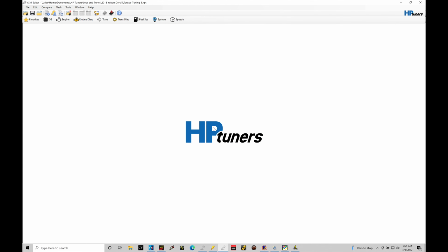Okay, so let's get started. We're going to be taking a look at our airflow correlation calibration within this tutorial. This is going to be specifically relating to our P0068 DTC code that can be thrown if we get in a situation where we're having more throttle angle opening past a certain airflow, mass airflow reading, or a certain MAP pressure range.